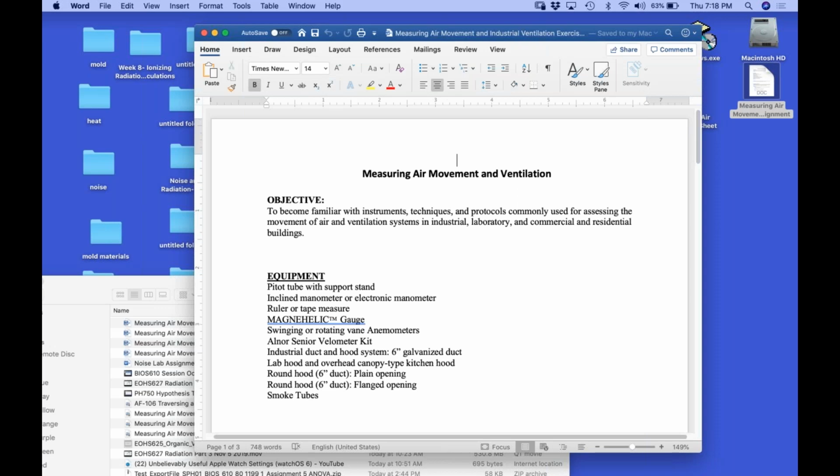I'm going to hold it there for a second. It's going to fall over. So we would normally connect this Pitot tube to this manometer, and we would see one side capture the total pressure, the other side capture the velocity pressure, and we would see the inches of water that were displaced. Well, we're going to use something else to do that now. And there it is. Let's try that one.